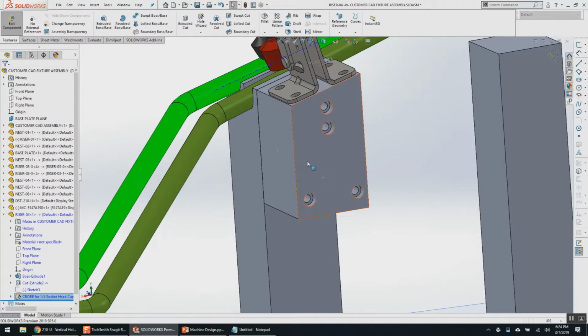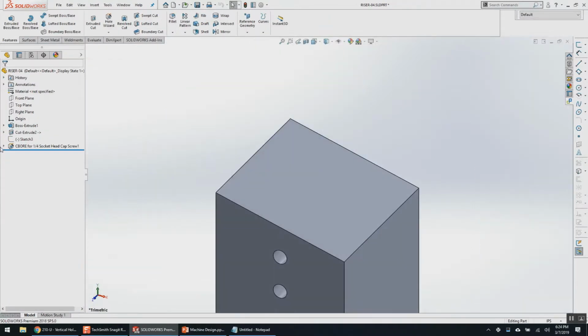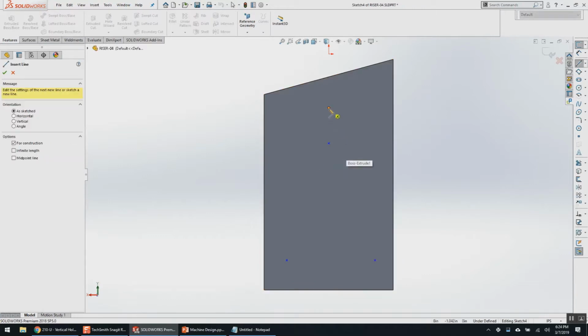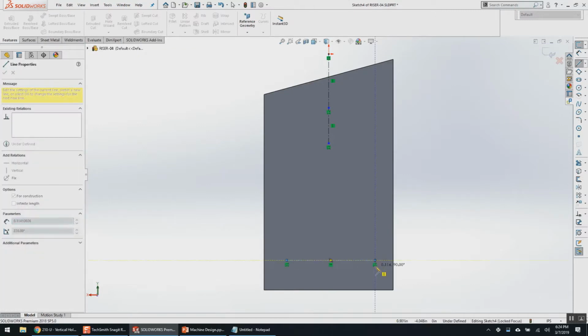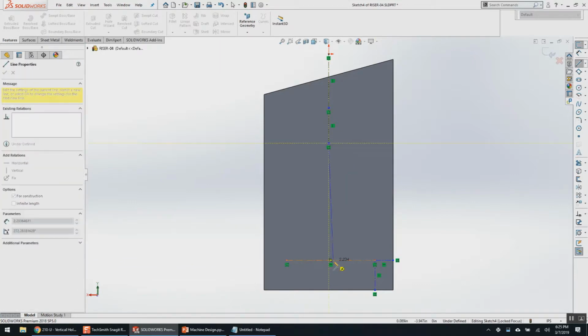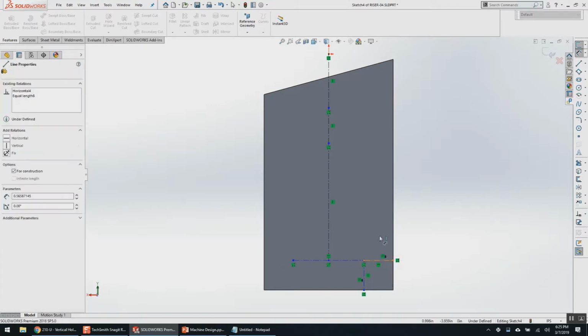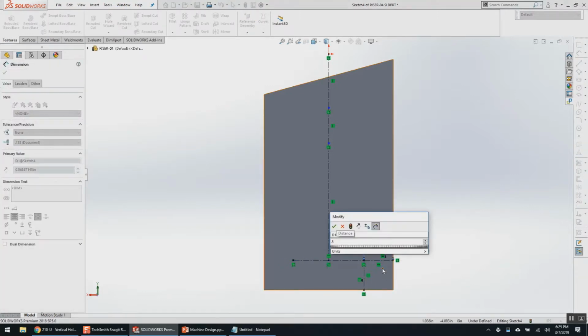Oh, we'll just put a couple in the middle, that'll work, and then maybe a couple down here. That sounds good to me. Pretend this customer doesn't care enough that the Destaco clamp is doweled, is possible. A lot of times I put holes in the design just so that I get the right machine position and I kind of know where I want them. And then I'll open up the part and define the rest of the holes later in just the part context, so it's a little bit easier to control.